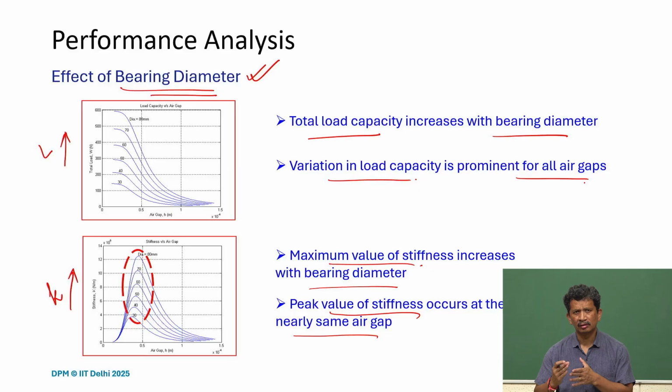So it gets reversed and then gets into an unstable region, and then there will be a humming noise and it vibrates very vigorously. Maybe the frequency is low, but it makes a lot of humming noise, and from that we can easily figure out that this is something not desirable, and we should avoid that.